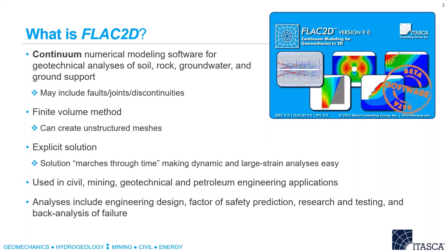It uses the finite volume method. You probably have heard a lot of people saying that FLAC uses finite difference. There is a subtle difference here. The finite volume method allows us to create unstructured meshes, so they don't have to be perfect grids. And this makes it very similar to finite elements.